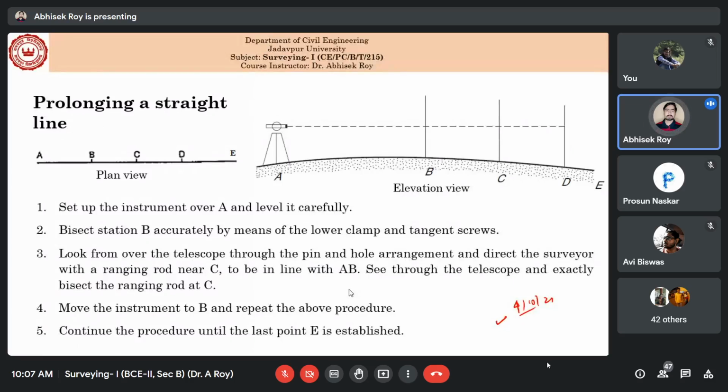In the traverse surveying, basically we will apply all this knowledge, how to calculate the horizontal angle, how to calculate the vertical angle, and we will plot our traverse. So all the numericals related to all these parts of theodolite will be there in the traverse surveying part. So obviously we will discuss all the numericals based on this usefulness.